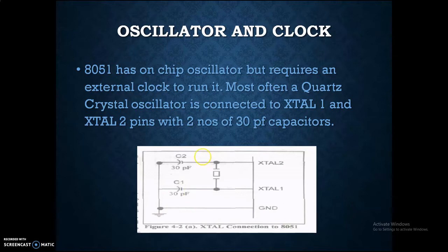We can also see these capacitors are not polarized. So we can use a 33 picofarad paper capacitor or disc type capacitor. What is the purpose of this capacitor? The purpose of the capacitor is to stabilize the output of the crystal, that is the frequency. So the frequency must be stabilized by connecting these capacitors in parallel with the ground. Okay,